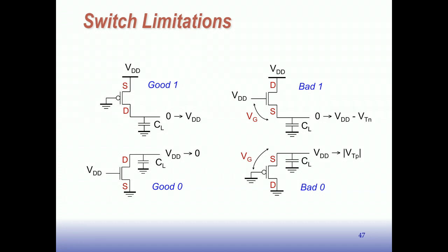And then the transistor effectively turns off. It hits its threshold voltage. So you can't get this point higher than VDD minus VT. Once this gets to VDD minus VT, then VGS is equal to VT, and the transistor effectively turns off. It's because of the built-in threshold.